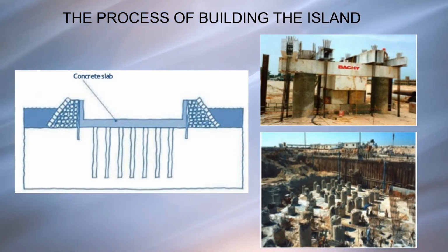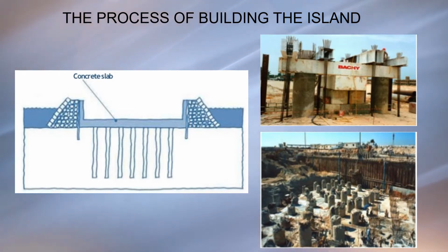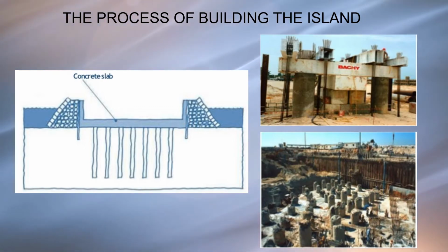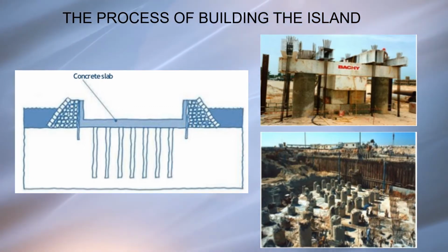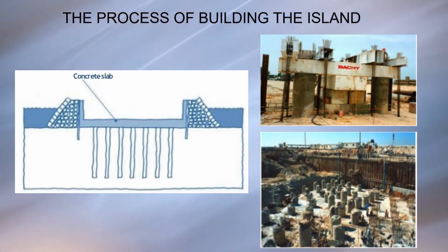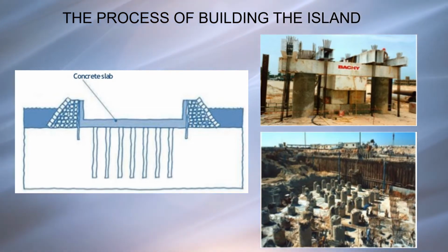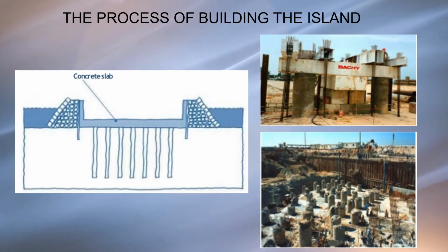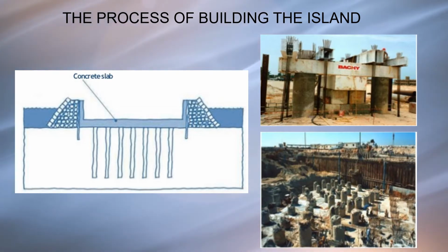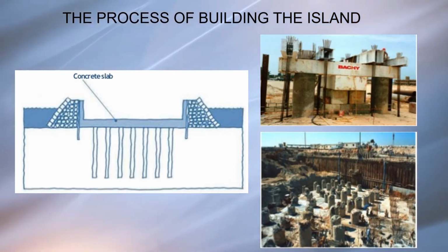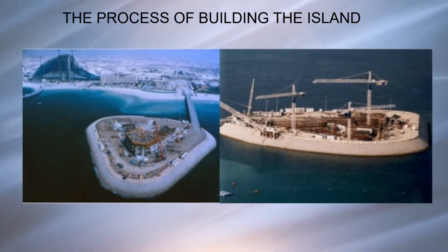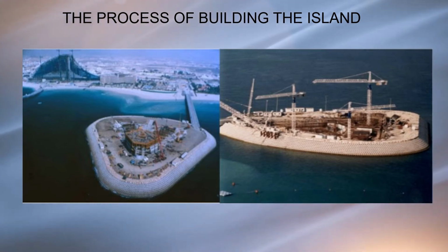Next, excavations began in the island to remove the hydraulic fill. A cofferdam was built while excavating. A 2-meter thick concrete plug slab was laid on the base of the island to prevent the base from popping out because of the sea pressure. A reinforced concrete retaining wall was also built. Then the construction of the basement started. The construction of the island was completed in 3 years.